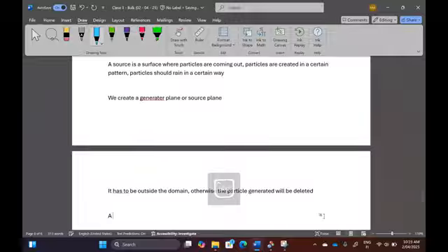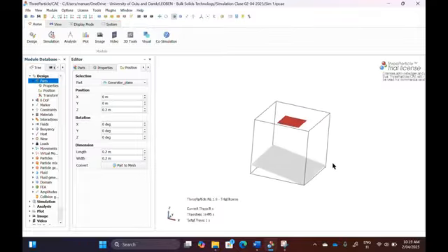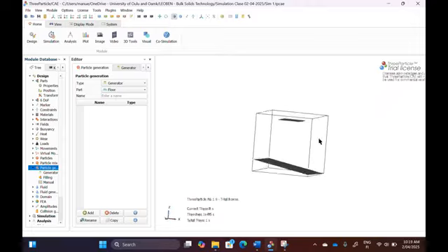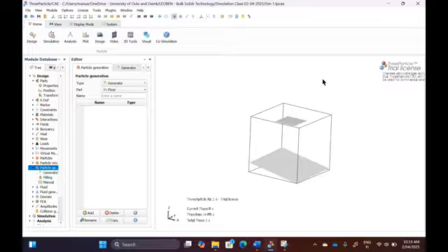Good. Now we need to find how the particles are generated on that plane. And this is just below particles, because it's called particle generation. That's that part. And I would more or less follow that structure: materials, parts, and/or particles, and then particle generation. Leave the other things out like collision, FEA, finite element, we don't need that for now. Let's go to particle generation, because we want to define how particles appear in our simulation. We don't want to have only one particle, we want to have a stream of particles, an ongoing stream.